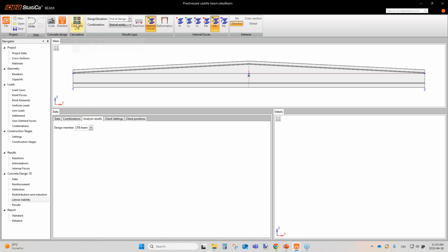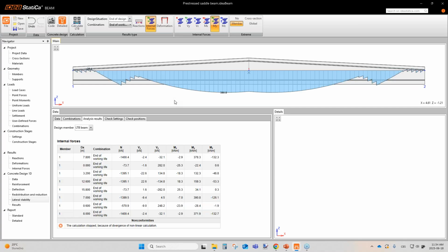In this step, I can launch the calculation, and now the geometrically and materially non-linear calculation is running. What we are doing in this calculation, imagine as we input the geometric imperfection in the first phase. So we literally curve the beam with the value of the geometric imperfection. This is an initial imperfection, and then we start the calculation, whether it is lifting the beam or transporting the beam. There is some increment of this initial imperfection given the calculation, and then we get the results.